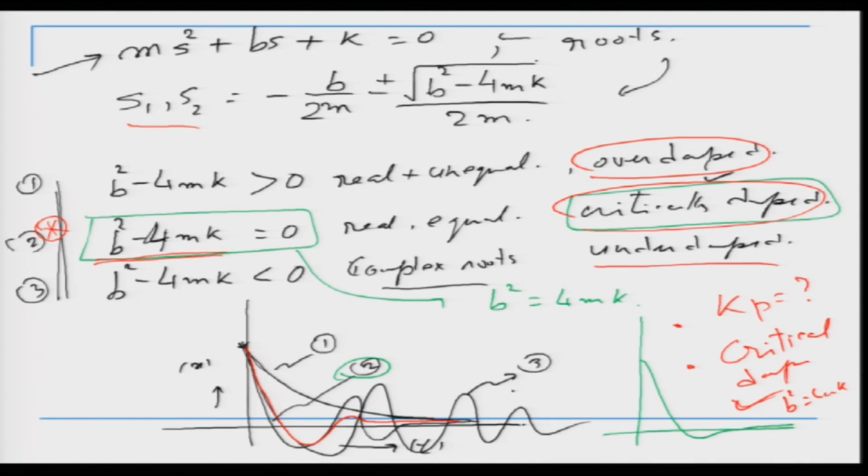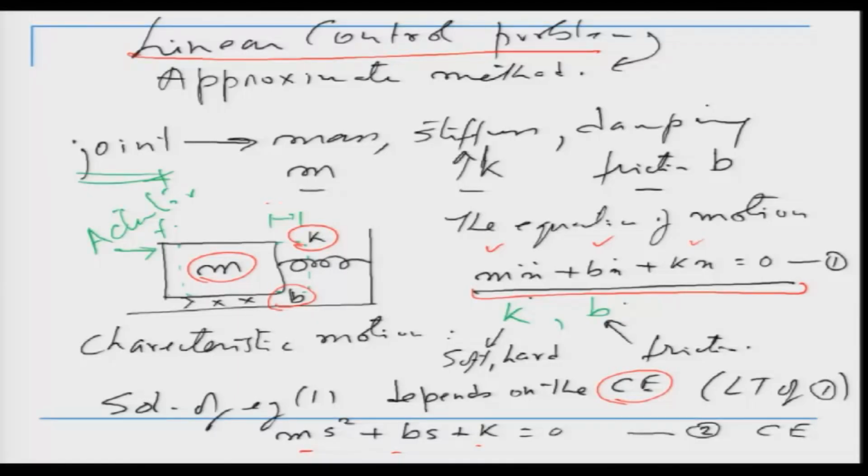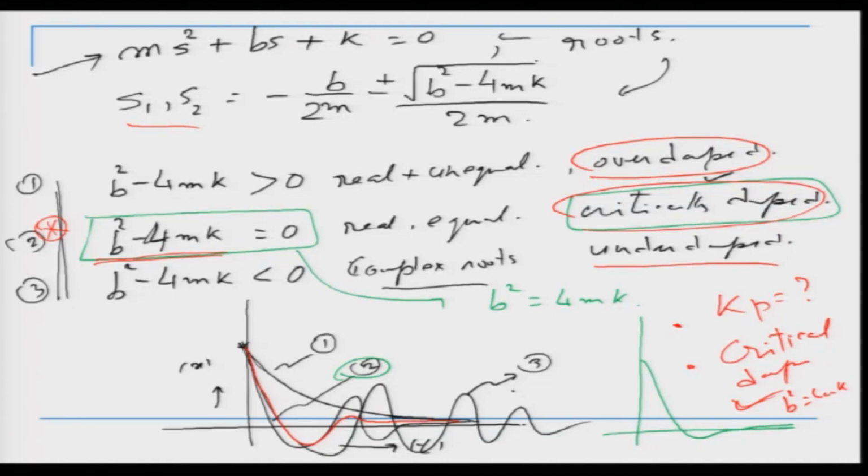The basic difference being a position regulator essentially keeps the position in the desired location. So, for example, if this is my spring mass damper and I disturb it a little bit here, now the controller will tend to bring it back and keep it wherever it was. So, it just maintains the position. That is a position regulator, whereas a tracking controller is the one that tracks a trajectory. The basic difference is that in a tracking controller we generate an error and then we try to make the error equal to 0. That is the fundamental difference, whereas in a position regulator we just try to keep it at the position.